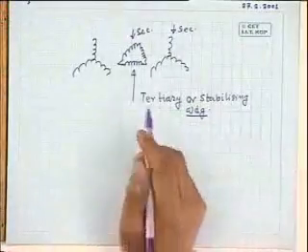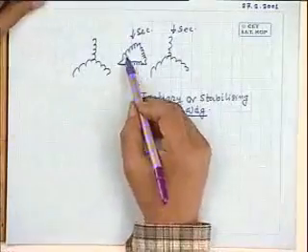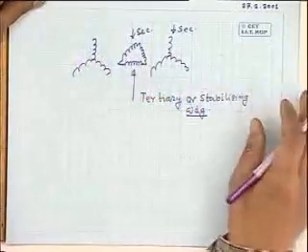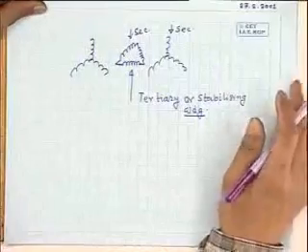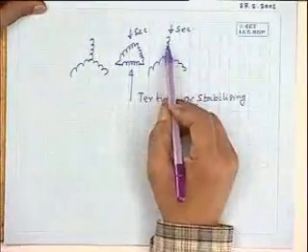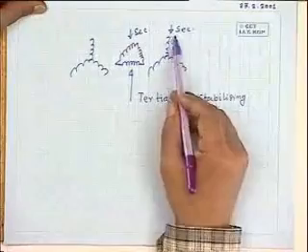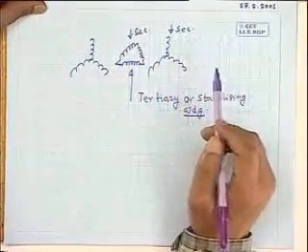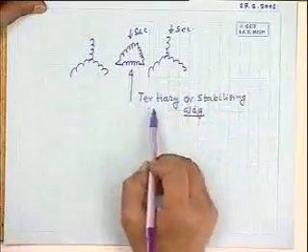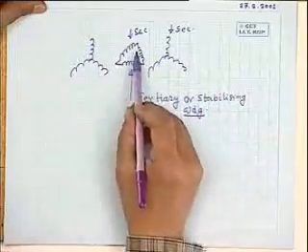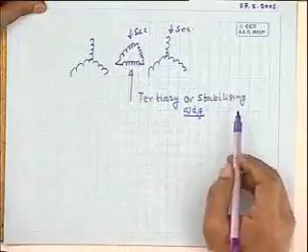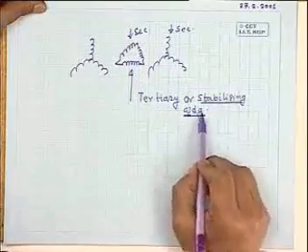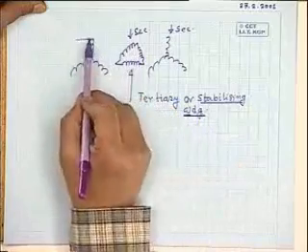In that case, that third harmonic current, magnetizing current, will be circulating in this delta, and it will try to make the flux sinusoidal in the core, and thereby making the voltage in the windings and the, of course, lines. It is already ensured the voltage nature will be more or less sinusoidal. So such windings which are provided, additional windings, are called tertiary winding. Why it is also called stabilizing winding, I will tell you.